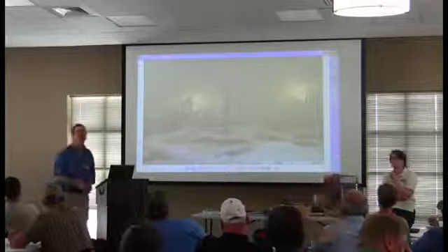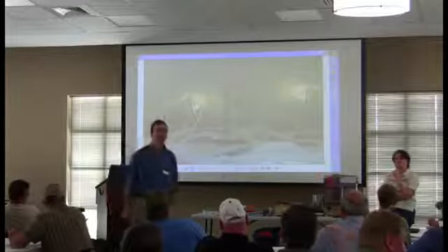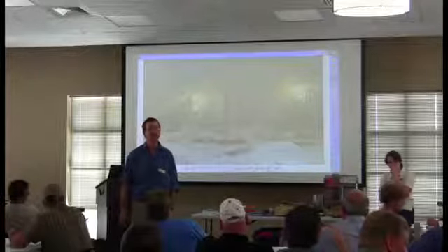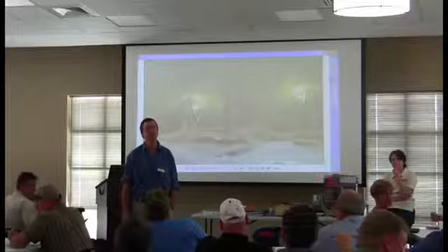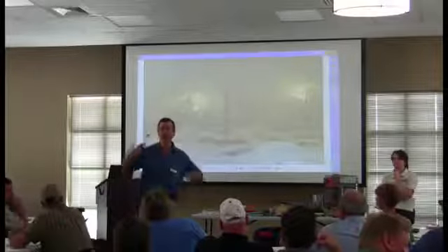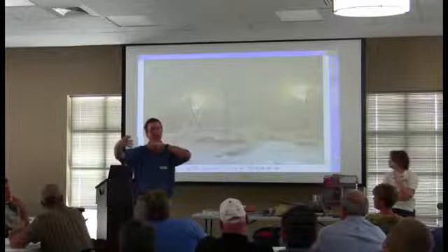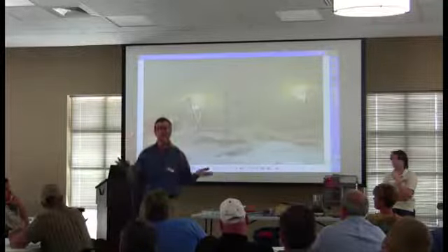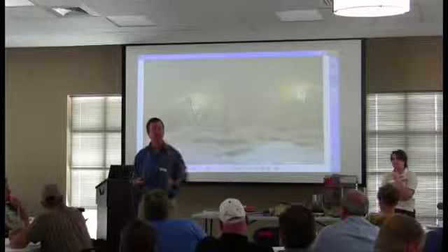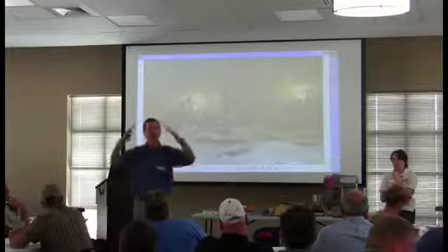If you do this application, you eliminate your vents. Correct. Will the building code allow you to do that? Yes. The question is, are you allowed to do this? If it's a straight gable roof, you also have to insulate the gable walls and everything, right? I mean, it's not an attic anymore. But the answer is yes, you can do this. And in essence, you're encapsulating the attic.